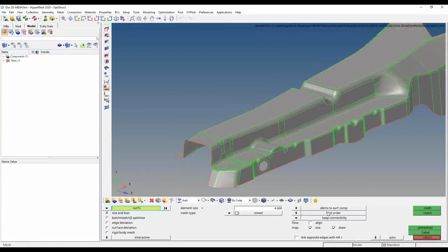Now, we can also access the AutoMesh tool. We learned yesterday the F12 shortcut key will bring that up automatically for us. What this allows me to do is simply select surfaces to create a mesh on, and I'm going to provide the surfaces as input, as well as specify the average size and the element shapes used to create that mesh.